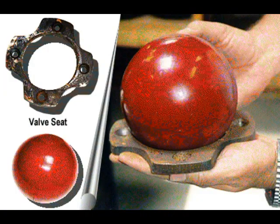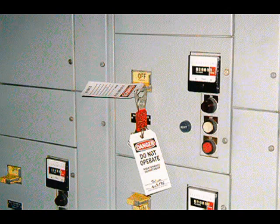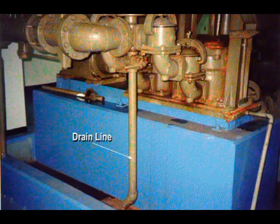Replacing the valve seat and gasket or the ball requires access to the ball valve chamber. The type of ball valve determines how to gain access. Specifically, before opening the ball valve chamber, be sure that the pump is shut off, locked out, and tagged. Then isolate the pump by closing the suction and discharge valves. If the pump isn't isolated, fluid in the lines will run out through the chamber. Relieve the pressure inside the pump by draining it so that fluid does not flow out of the ball valve chamber when it is opened. Let's look at some more.